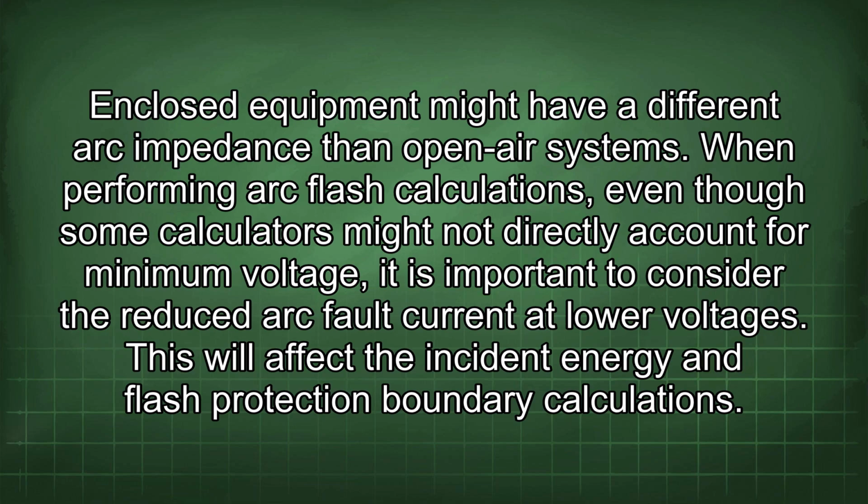When performing arc flash calculations, even though some calculators might not directly account for minimum voltage, it is important to consider the reduced arc fault current at lower voltages. This will affect the incident energy and flash protection boundary calculations.